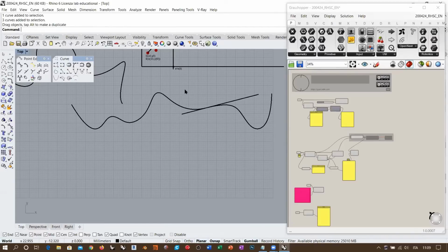So for example, we have been saying from the start today that the main problem with the control point curve, which makes plenty of users prefer interpolated points, is that you cannot directly define the passage of the curve through a precise point.